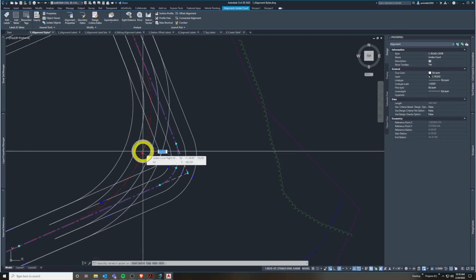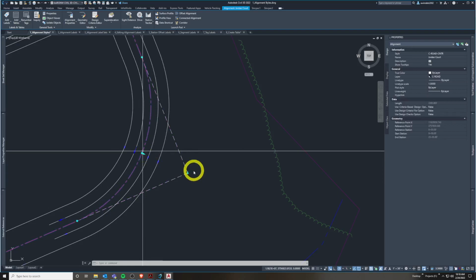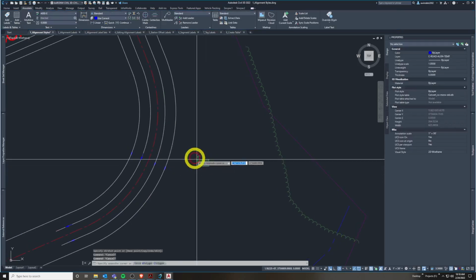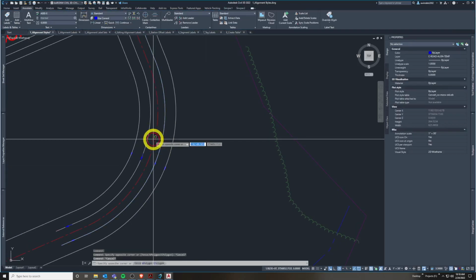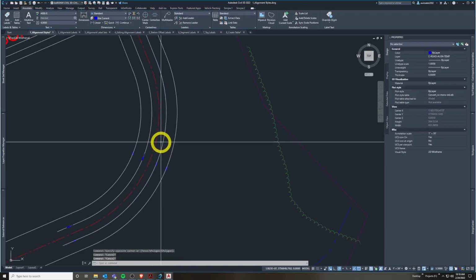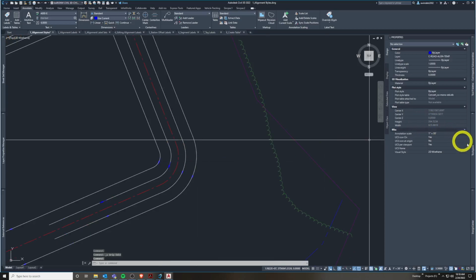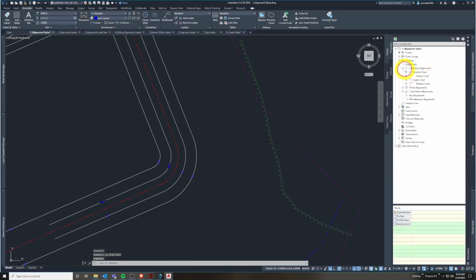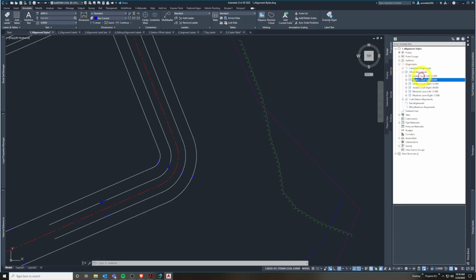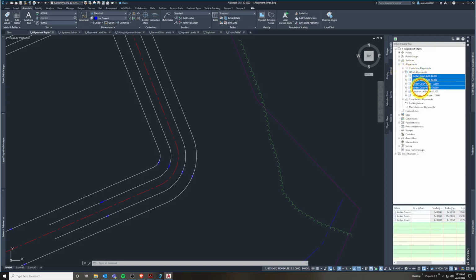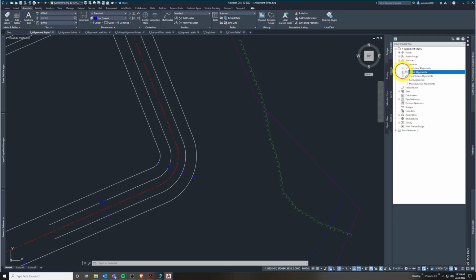There's the 12-foot ones in the middle there, and there's the 30-foot ones. They're designed to move dynamically with the center line alignment. So there's some dynamicness and interconnectability with Civil 3D in that way. So that was just showing you graphically what I explained here between the alignments, how they're interrelated. We have all 4 of these for Jordan Court that I just moved. They're all connected to the center line one.